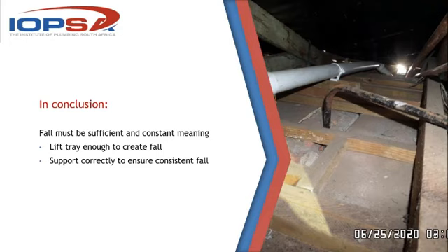How many installations do we come across where you'd ask to replace a geyser, but you haven't really checked how much fall you need for the drip tray pipe, so you replace the geyser on the same supports that were there, only to find that you have to put your tray discharge pipe level because there's not enough fall. So please lift your tray when you're replacing a geyser or when you're installing a geyser.